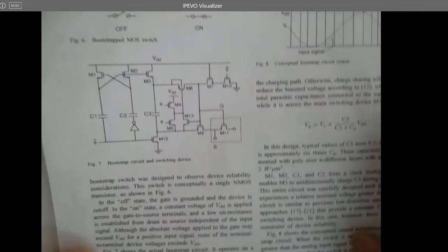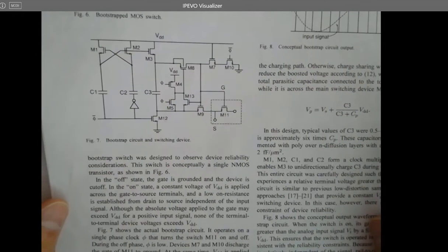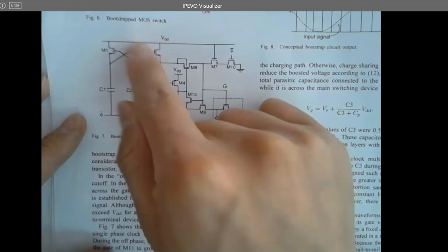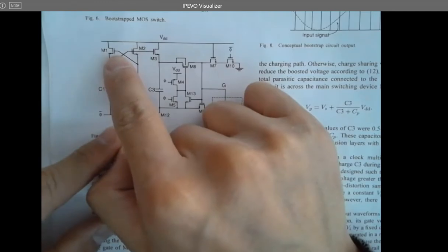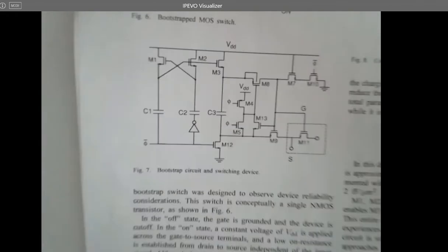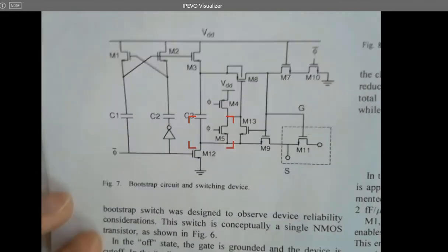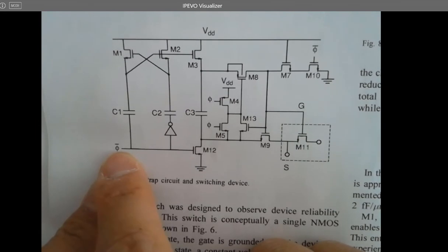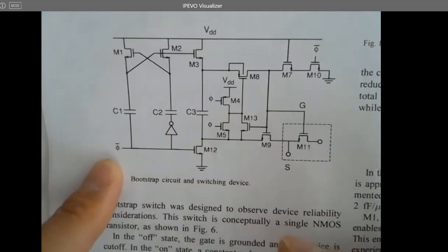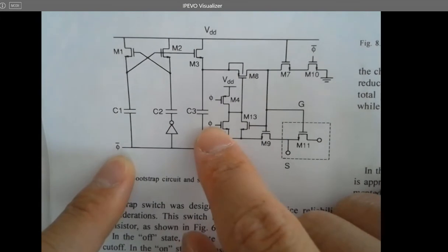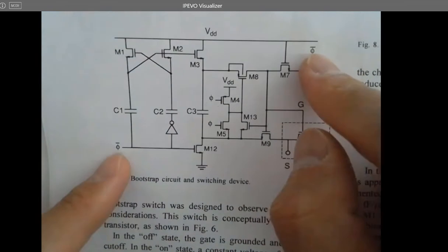And here's a circuit to implement that. So let's take a look at this circuit, how this works. This part, keep in mind, is nothing but a charge pump. Remember, if you have an NMOS here and a capacitor here, and here's the signal, here's a clock. It has different phases. This is phi. It's pronounced as phi. Phi bar is just the inverted clock, and because they have phi's here as well, that's a clock in phase, and that's 180 degrees out of phase, just being inverted.